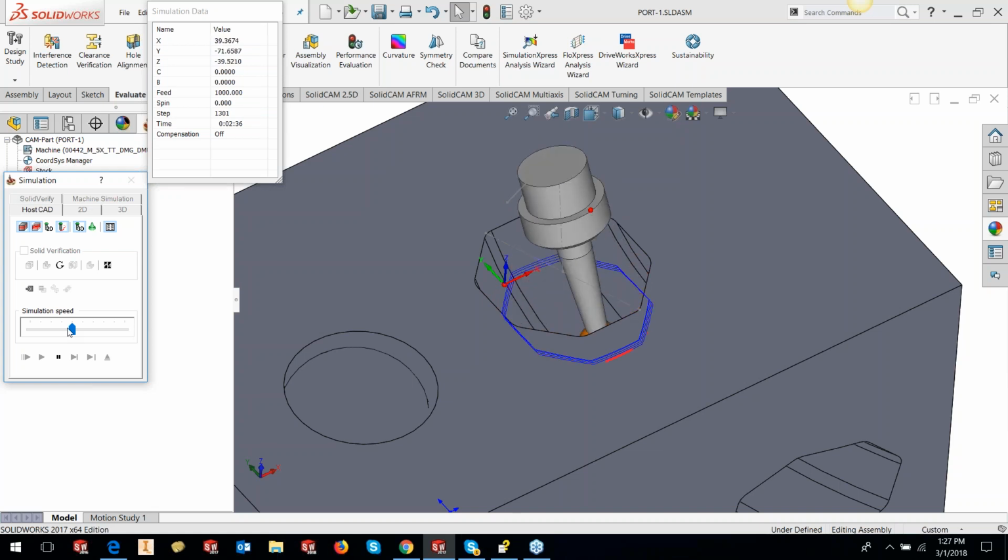So you can actually machine any geometry which you feel is bad or extremely difficult to control your tool axis. You can create a much simpler surface, machine that simple surface, and just project this tool path using the gouge check onto those complex surfaces, where the tool axis will always be pointing towards that simple surface and actually be machining those complex surfaces.